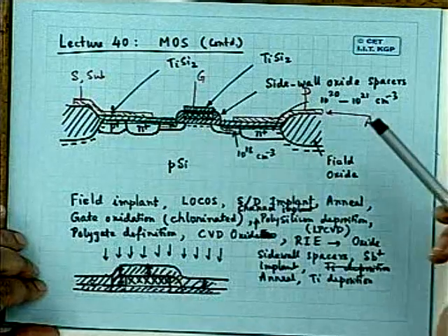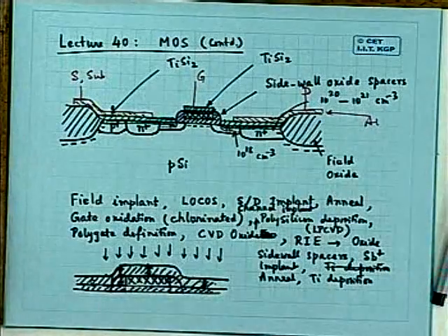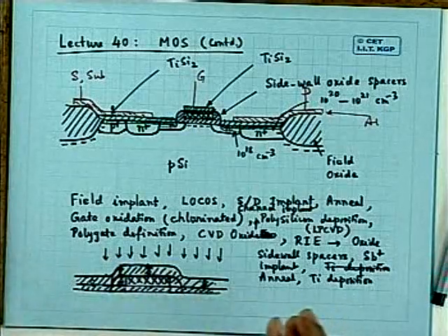Because in that implantation, if the ion beam is a directed, parallel beam, and silicon being a crystal, as ions are entering, they see a lot of channels, open spaces. The atoms are very nicely arranged. In certain directions, you find almost hollow spaces called channels. So the ions penetrate unnecessarily quite deep, and there is uncontrolled implantation. This is called the channeling effect. To avoid that, two things are done. Either you implant through a thin oxide, in which case the ion beam gets scattered, so the channeling is reduced or practically stopped. Or do the implantation at a slight off angle, about 3 to 4 degrees. Therefore, it is customary to use channel implantation following the gate oxidation.